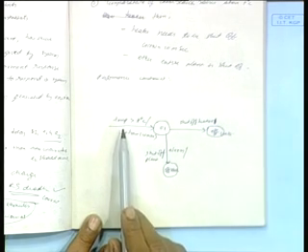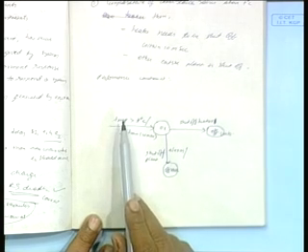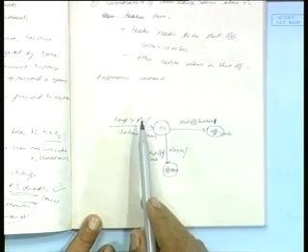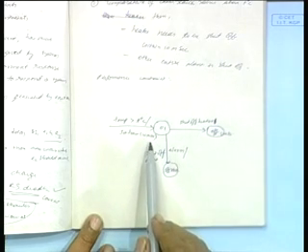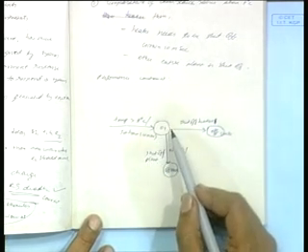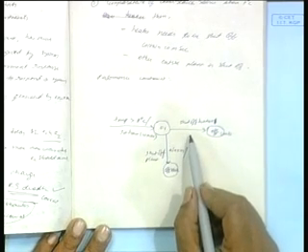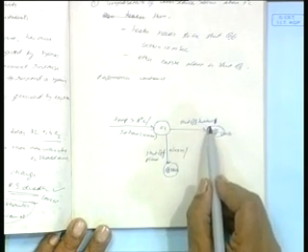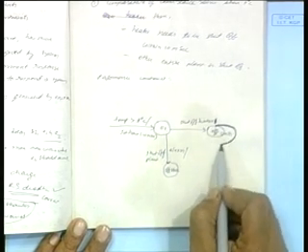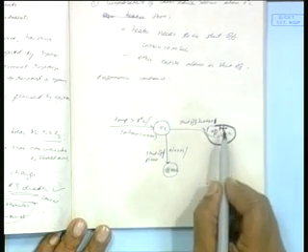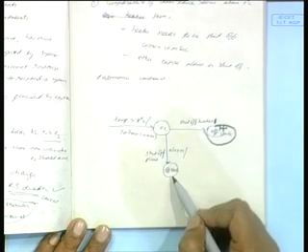So, if the temperature is greater than T degree centigrade, but this is a condition, no? It is not an event. Okay, the event of temperature greater than T degree centigrade. Set timer to 10 millisecond and then it enters a state called E1. And then if the heater off event occurs, then it goes to the heater off state, is it? Heater off state, and on alarm it shuts off the plant.